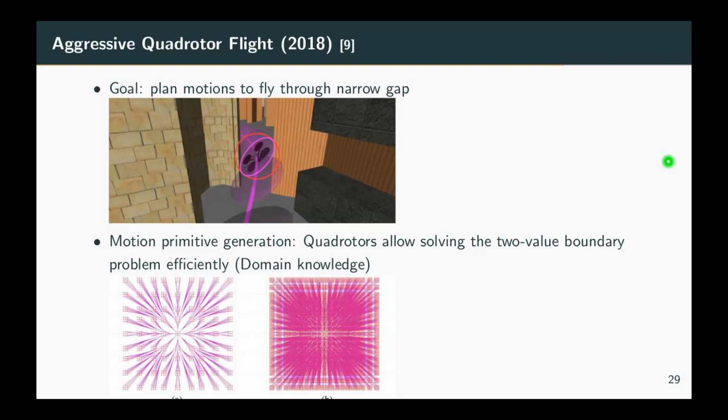And if you want to move quickly, in principle they could move on a straight line, but then every single time you would need to brake. So you can move like this, brake, and move like that. But that's obviously not as efficient as if you have a smooth curve. So for time-optimal quadrotor flight, you're always interested in smoother movement.